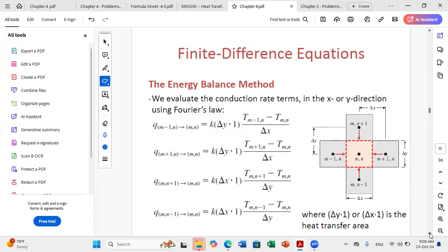And now, as we said together, we will compute these fluxes for the different phases. So you can say, when I assume that the flux is entering the cell, the temperature of this node should be larger than the temperature of this node. So how can I write, if you want, delta T over L, it's the temperature at this point, T(m-1,n), minus the temperature at this point, T(m,n), over delta x.